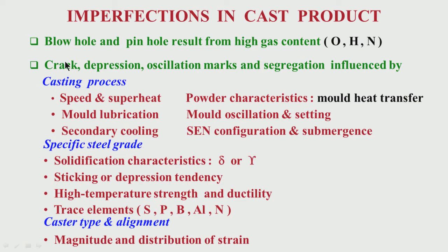So, these are important, whether they can withstand all those stresses, all that pressure, ferrostatic pressure from the liquid inside, or at the surface of the solid shell there are a lot of pressures, as I mentioned, during bending, during straightening. So, whether the shell can withstand those stress or strain will finally decide whether there will be crack formation or not in a solid shell.